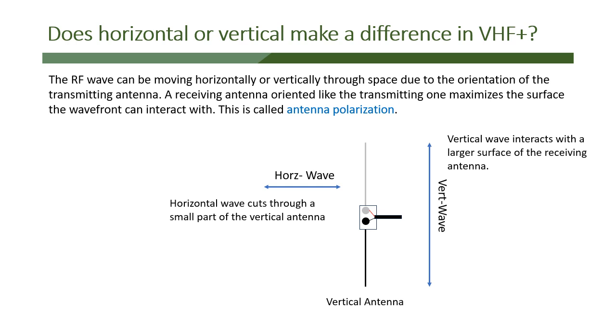And so by convention, when we're doing frequency modulation, FM transmission in the VHF and above ranges, we use vertical polarization. That is, both antennas are set up to be verticals. And in the VHF and above ranges, if we're using what's called SSB, which you'll learn about later, single sideband, or data transmission, we often will use horizontal orientation.